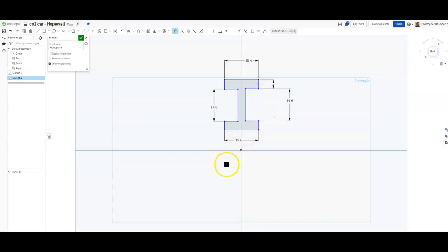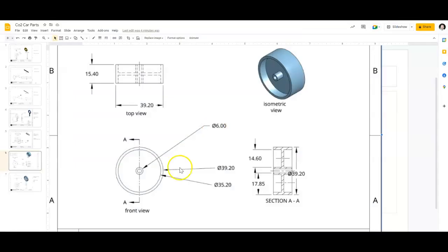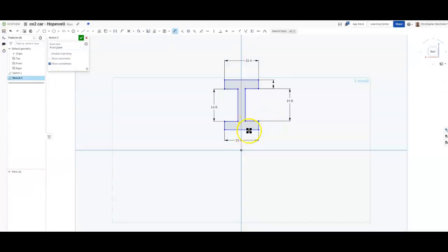The next step depends on whether you want to revolve around an additional line and cut out, or if you want to cut out the center circle after, right? If you want to cut this hole where the diameter goes in after, you can do that. Okay? If you don't, that's also fine. But in short, I'm just going to dimension this to be 3 because 3 and 3 gets me to 6. And I think that is easier math, but if you did this a different way, that is also fine, right?